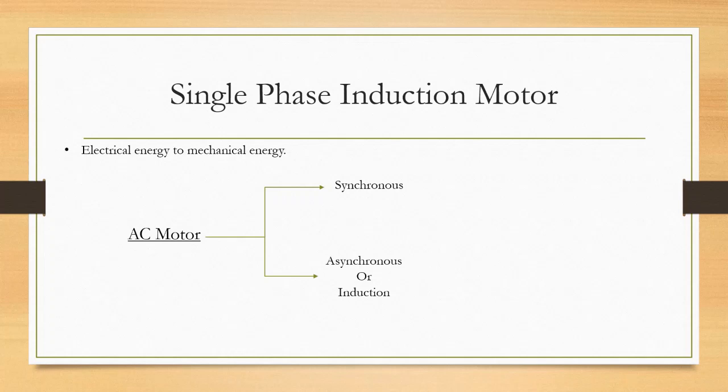Because of the interaction between the stator field and the rotor field, a torque is developed. So the rotor will rotate. This is the working principle of a three-phase induction motor. So in three-phase induction motor, we have rotating flux.